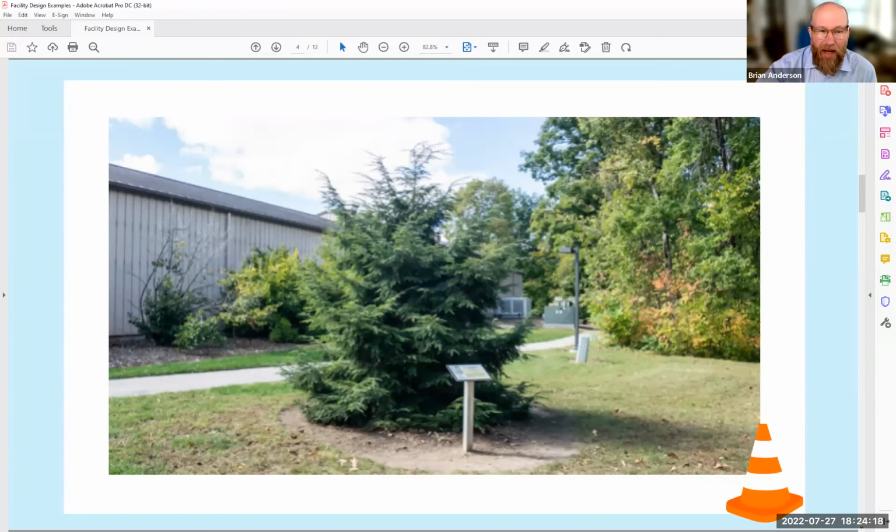And so that gap, there's often an air gap or a very poor type of seal to keep the air and the rodents and the insects out of your buildings. Right around, we call that the skirt of the building. And that's a really important place to look for damage and leaks and possible infiltrations.